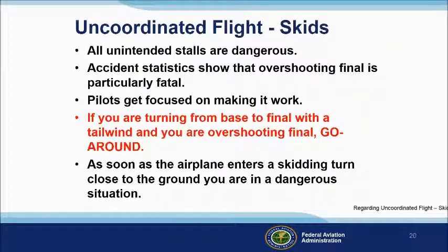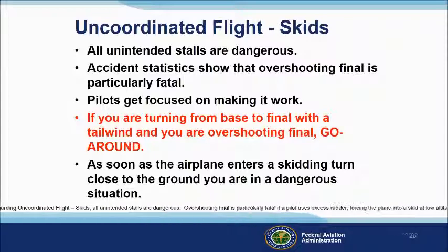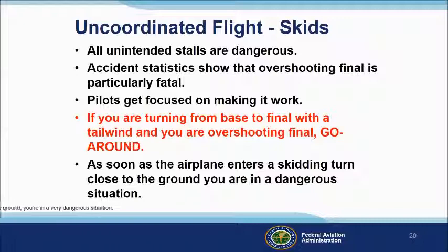Regarding uncoordinated flight, skids, all unintended stalls are dangerous. Overshooting final is particularly fatal if a pilot uses excess rudder, forcing the plane into a skid at low altitude. Pilots seem to get focused on making the approach work out. Be aware of this and do not let your desire to land overcome your awareness of what is happening to the aerodynamic forces out on the wing. If you are turning from base to final with a tailwind and you are overshooting final, go around. If an airplane enters a skidding turn close to the ground, you're in a very dangerous situation.